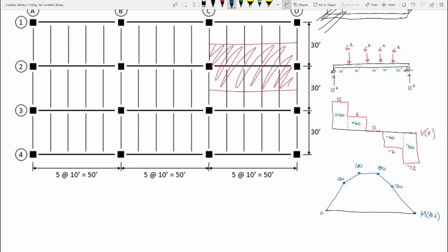But you see what I'm talking about? Like in terms of the magnitude. So those girders, think in terms of size, they're going to be a lot bigger than the beams, right? Because they're responsible for more. Okay? With me so far?